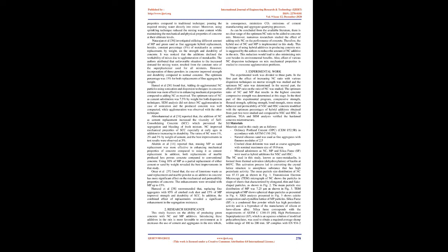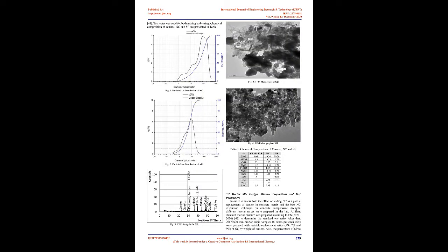The main hurdle in using NC as an additive to concrete mixture is the discrepancies in literature about defining its optimum ratio in concrete mixes. Many authors attributed that to the dispersion techniques of NC during mixing. Defective dispersion forms NC agglomerations in the matrix, causing weak clogs that restrict the hydration process. 32 to 34. Authors previously applied several dispersion techniques as stirring and sonicating to solve agglomeration problem 32 to 34.